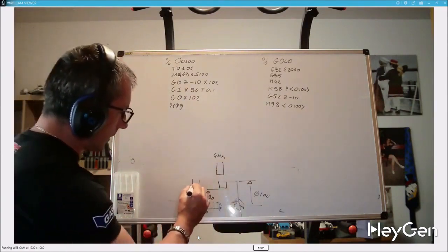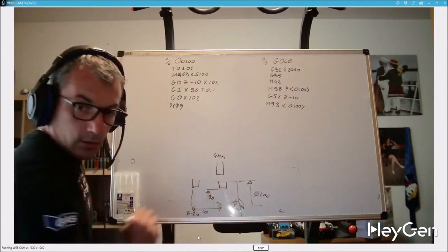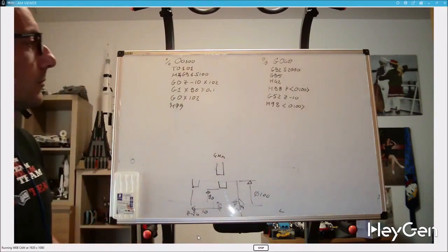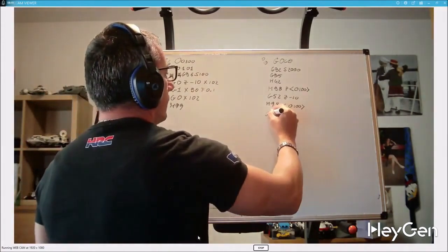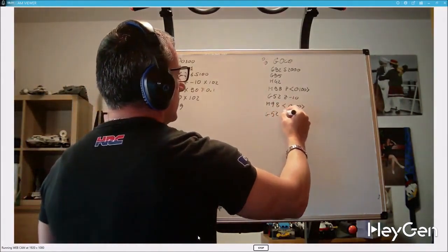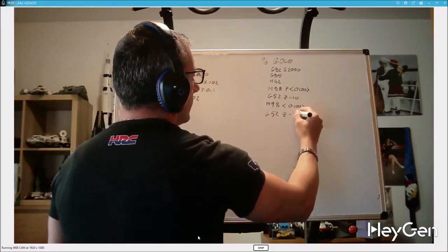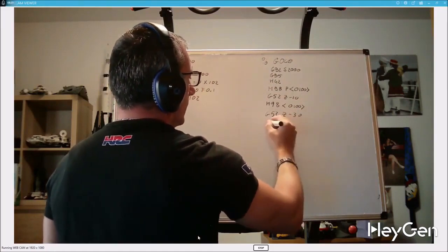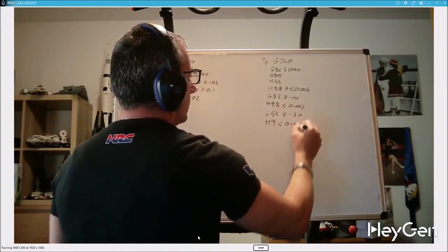So the program is repeated, shifted by 10 millimeters, which means it will no longer be Z10, but Z20, physically for the machine. I then want to do another G52, Z minus no longer 10 millimeters, but 20. So Z minus 30. M98 P0100, and here it gets convenient.